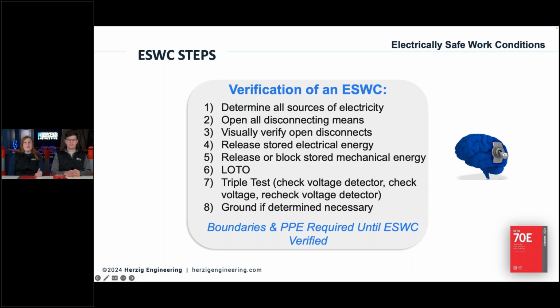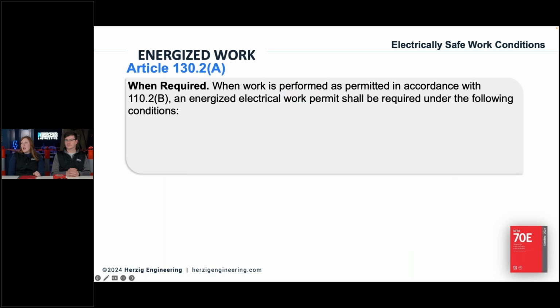People still can't approach during this process. You still got to be protected during this process. The other side of it is, okay, let's say the times that you actually do have to perform energized work. And I'm just going to make a real quick note here. It should be infeasible to do de-energized, not inconvenient.